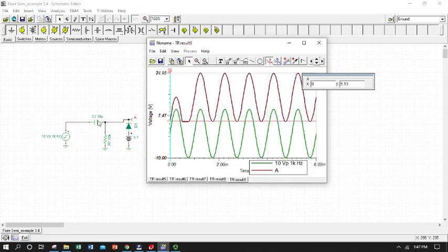The capacitor's not going to charge, so it's not going to develop an opposing voltage yet. It doesn't have time because we've put this big resistor, and of course the diode's in backwards. It's in reverse bias from the standpoint of the source. So we sweep up our forward cycle, and our red curve, which is our output, just tracks it basically.